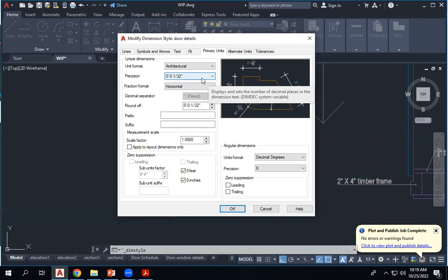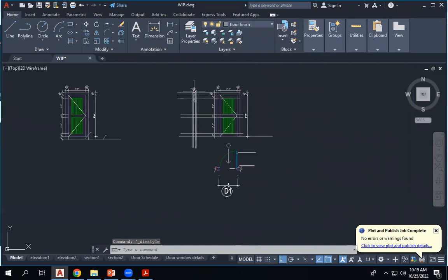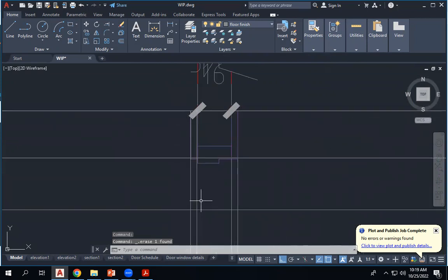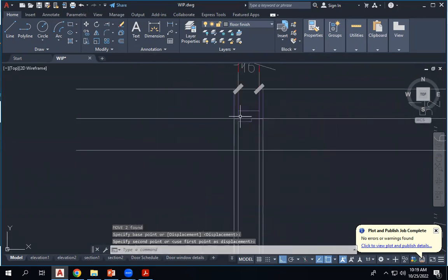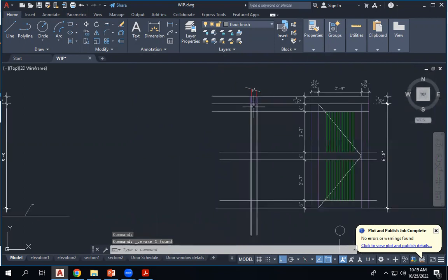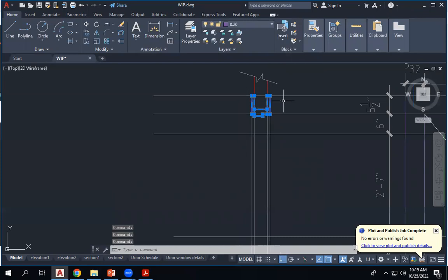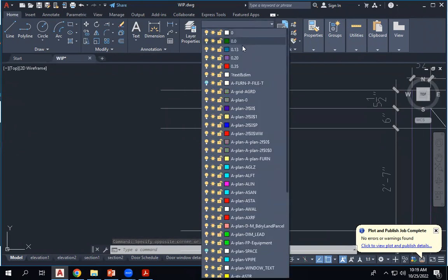Orange. So I will take. So it will be like this. Now the two architrave, this section should be in point 2, and the lines showing the architrave at the far back should be on the layer point 0.